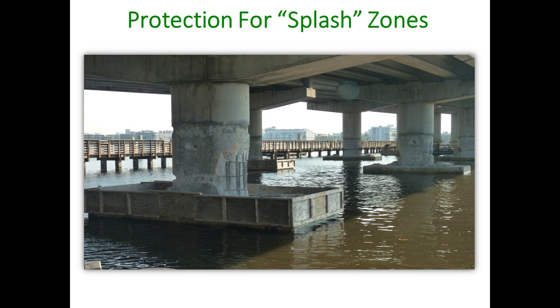So this is just a couple of pictures of one of the systems being installed. You'll go in, and of course you're going to have some delaminated concrete. Any repairs that you have to do, you're going to come in and remove this delaminated concrete. With all of these systems that I've talked about, you're going to want to make sure that all of your steel within your structure is continuous.